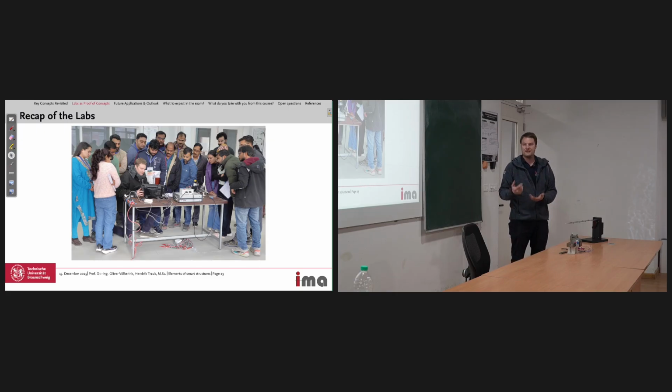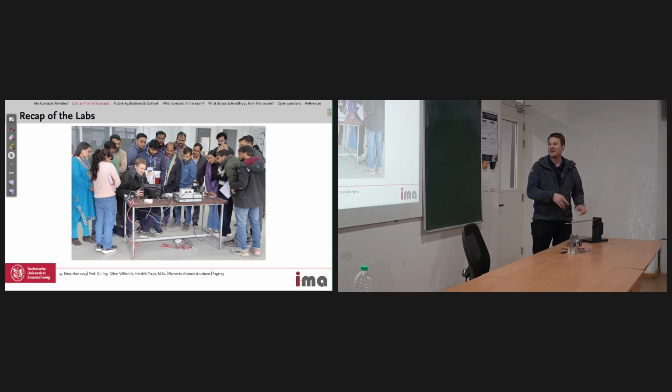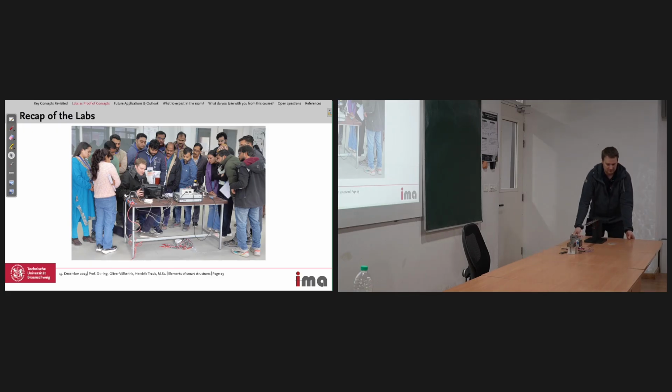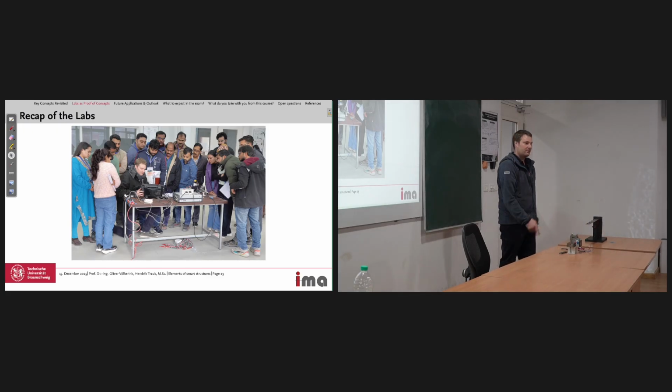And if you do it for yourself, then sometimes it makes a lot of sense to put another sensor on the clamping or on the desk even. So we had some experiments on a simplified wing model where we had a sensor here on the table and the wing here on the table, and everything was massive steel. But anyway, then we got some really terrible noise and we couldn't identify why. And then we had to look at the table, and then it was clear that some vibrations went through the table into the sensor. So what we then did is we used two tables, completely separated, and then the signal got much, much better.